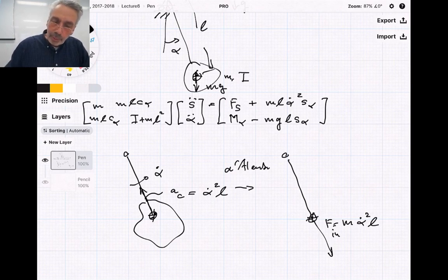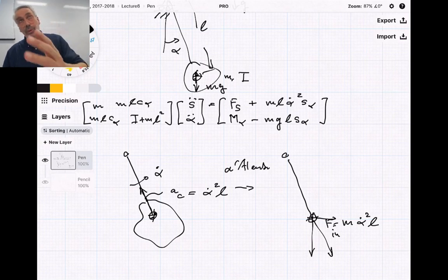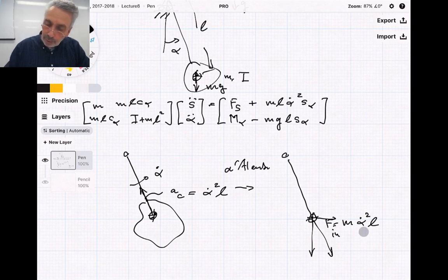But now, apparently in the linear direction, we have a component. Yeah, that's true. You can decompose this force in two components, a horizontal one and a vertical one. Well, the vertical one is what the support takes away. That's a constraint. And the horizontal one, that's a free force. So that's moving the thing. And that's this thing times sine alpha. So yeah, I'm sorry, it's sine alpha. By physical insight.